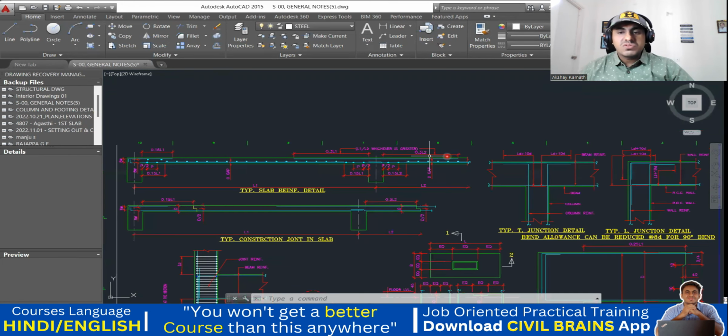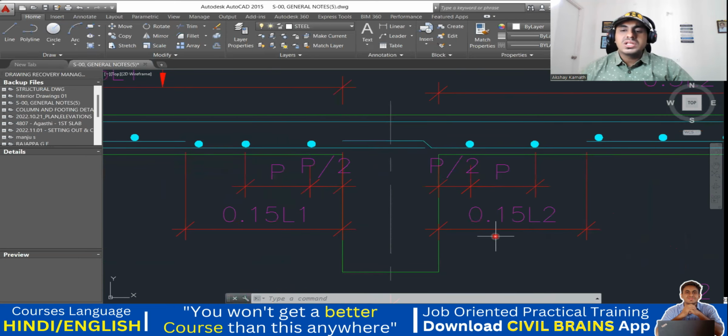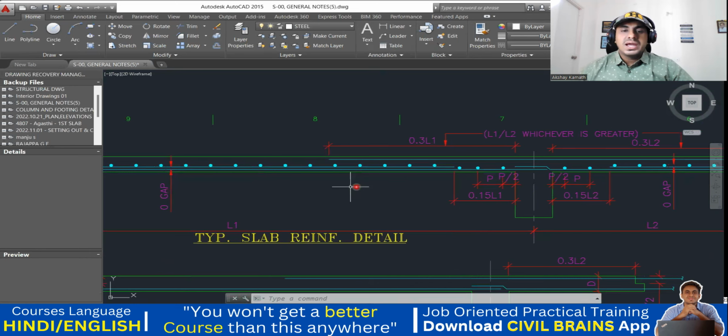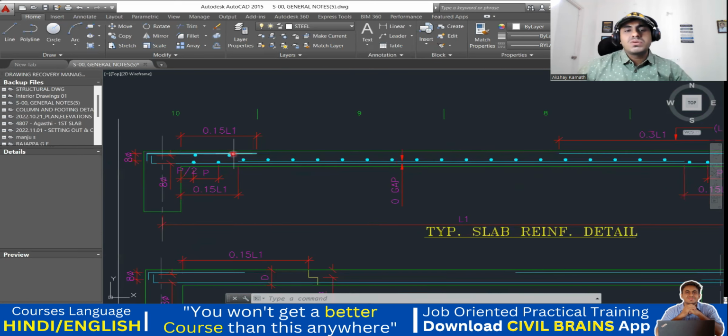The same thing here also, everywhere. And then lapping again, same thing. Whatever you did in the beam, same lapping. You can lap the bottom bar near this junction, that is your column-beam junction. And top bar, anyhow, there won't be a lapping in the top bar in case of slab and all. Okay, fine. Top extra bars will extend only 0.15 into L1.